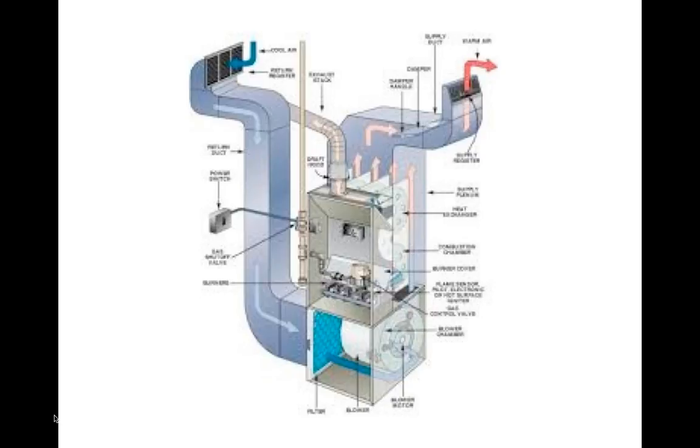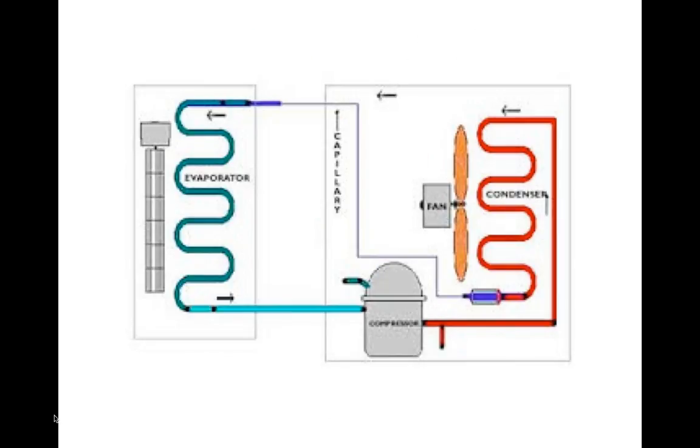When you have a home unit, this is probably what it looks like. You have a vertical unit. It's got a gas heating device on there and a heat exchanger. You blow air through the heat exchanger so you don't mix it with the actual burning gases. It goes up into the house, comes back down through a duct, probably on a wall somewhere, all the way back down to the unit, and it's recirculated over and over again. And notice, like many home heating units, it doesn't have a fresh air intake. There is a little flexible metal duct coming out of the top of it and going to the left, a small round one. That's an exhaust for the exhaust gases from that burner in the bottom. That's not a fresh air intake.